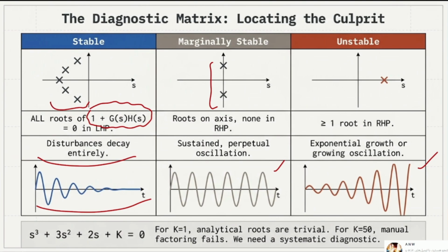So why do we care about all of this information from the beginning until now? Because, as I just talked about, there is one important element in most transfer functions that we call gain. Most of the time we consider the gain as 1, so it isn't an important issue for us. But imagine you have a system whose gain is so high that the location of your poles is going to be different. At that time we actually care, because we have to see what would happen to our gain.